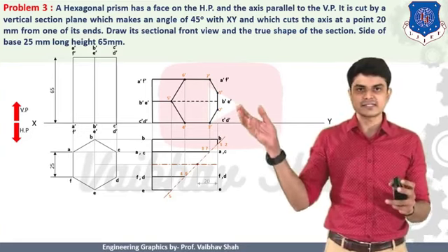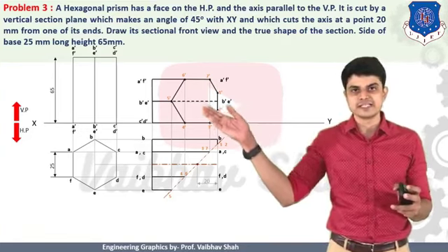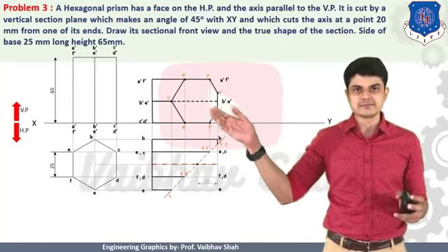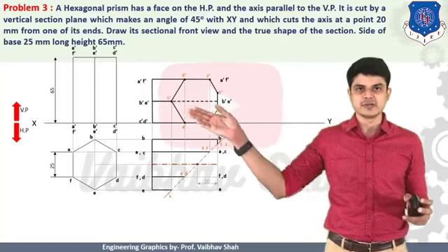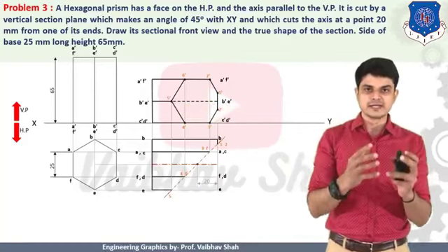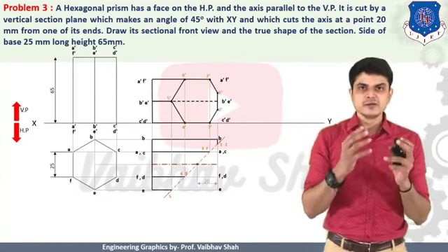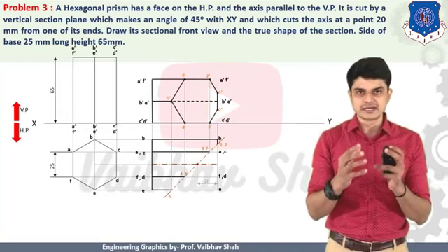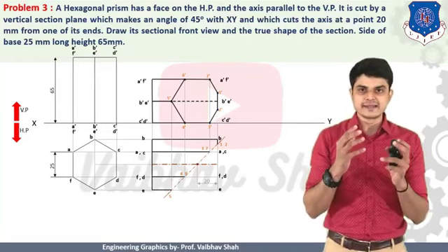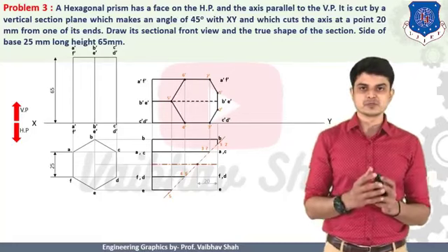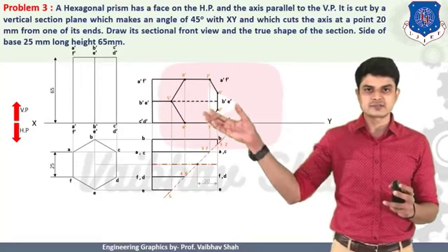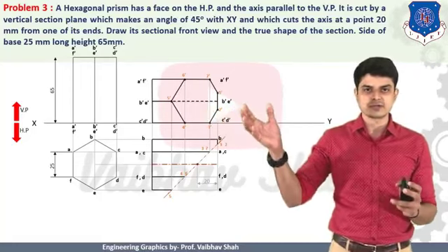But here in the cut section, we are not having any E lines. We can specify this dotted line. But here we are having point E and solid lines. We should plot that solid line. So always remember, when you try to join the points, and if you are having the dotted line and solid line at the same time, you should give preference to the solid line. So in this case, we have drawn this solid line darker, and this is your dotted line.